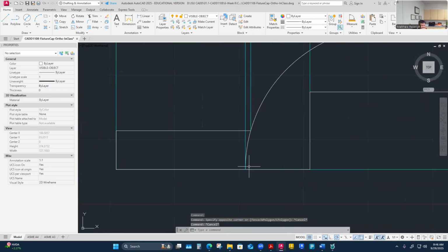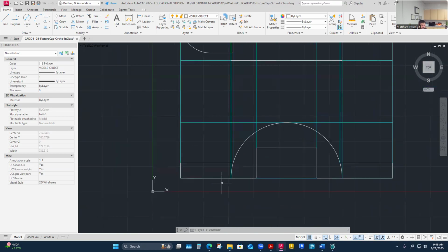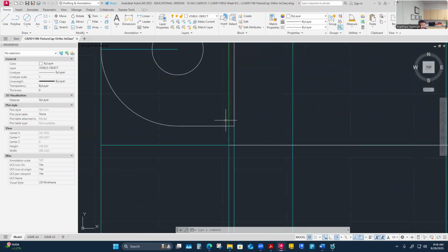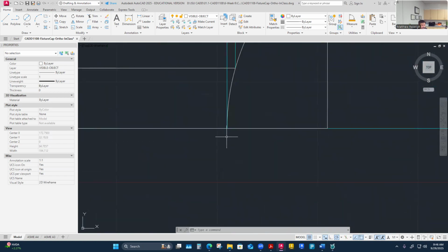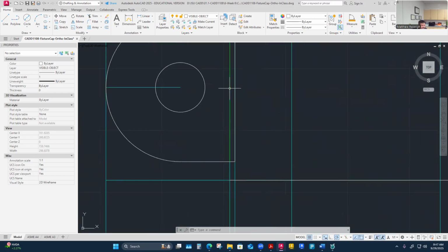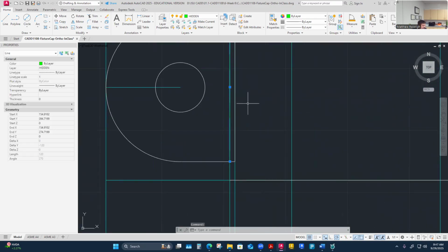Because that's kind of this surface that would be on the bottom and where the ear meets. I think I'm going to omit it because it's not really clear if you would have it. Where this surface meets the surface of this, it could be blended out so well, or it could be a uniform shape, right? We don't even know what material this is. It could be 3D printed plastic for all we know, and then it really wouldn't have this hidden line. So the argument is if there was something going on here, a separation of surfaces, maybe I would have a hard line there that would show up as a hidden line. But I think in this case, there's probably nothing there. It's going to look like those surfaces blend together.